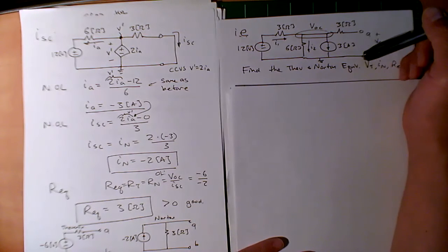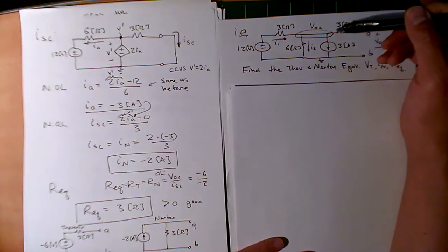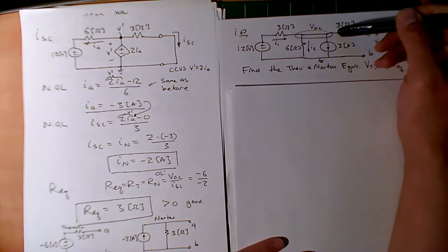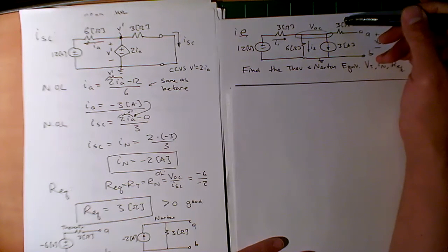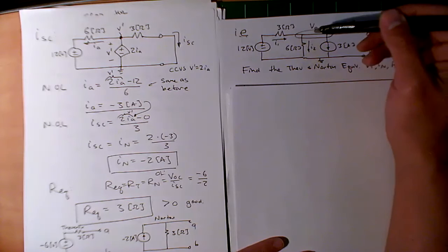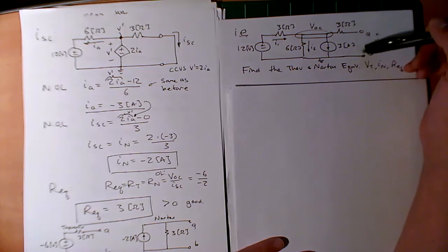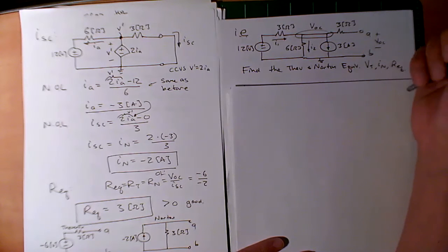We have the open circuit voltage, good. So this is VOC, which is VT. Again, we had that similar trick: no current here, which means no voltage across here, which means by KVL this node voltage, from here to that ground, is the same voltage as the VOC. So actually that node voltage is VOC. That's a nice little trick.